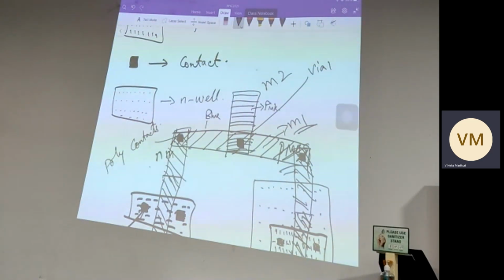All these in your CAD tool will be differentiated by different colors or different design combinations. So via1 can only be used for connecting M1 and M2. Via2 has to be used to connect M2 and M3.